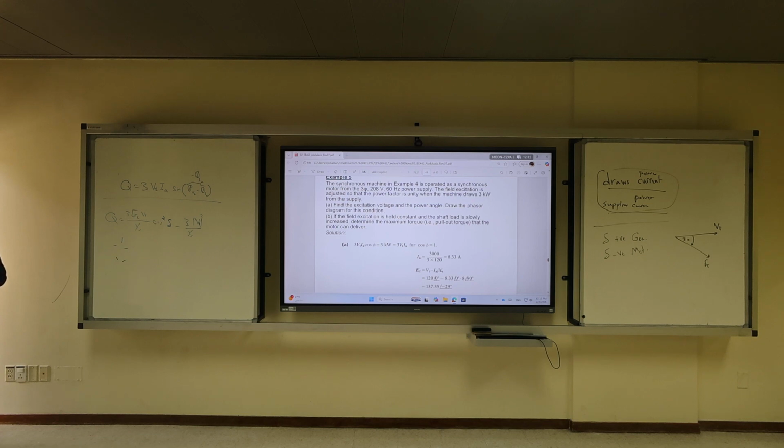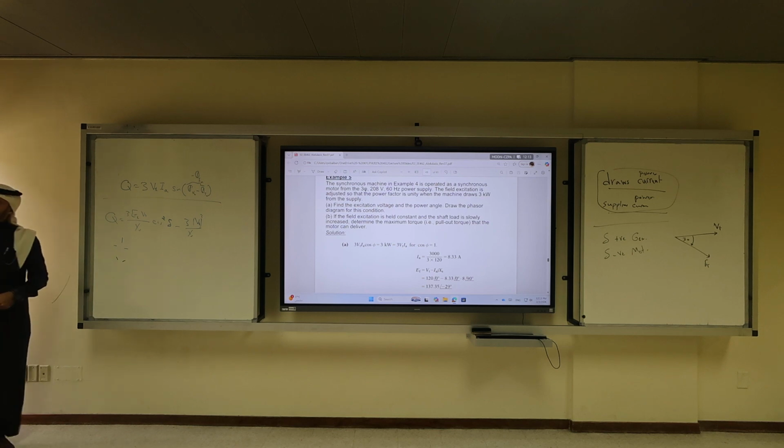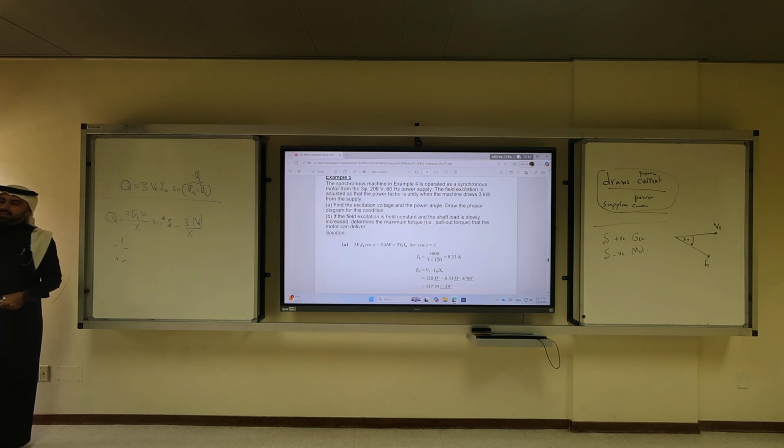The other thing is always check the outlet of your electric oven. Sometimes even if it's burned, the current would still flow. So my advice to you, go to a certified electrician and check. Do this calculation. Check your electric oven power, divide it by the voltage, divide by 220, or divide by 220 over square root of 3. Single phase, it is single phase. Divide just P over V, no threes. Get the maximum rated current, have a margin. Let's say the maximum current is 10, buy one that's rated for 15.